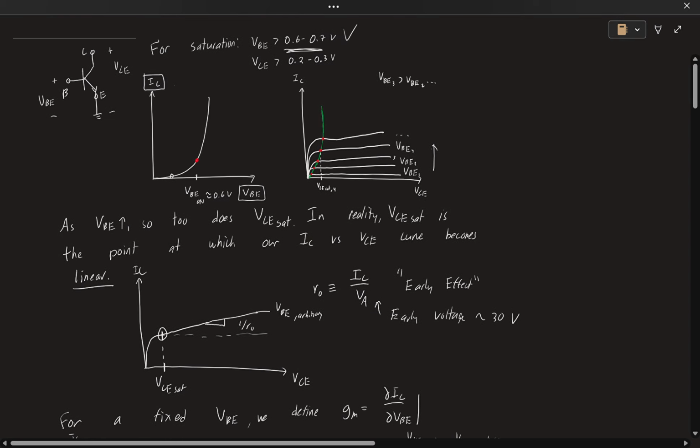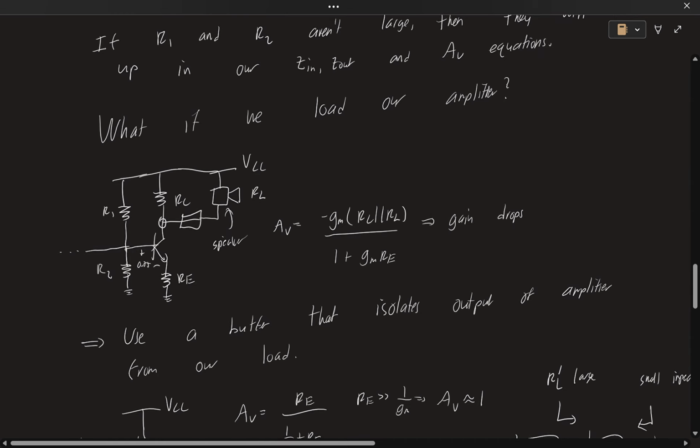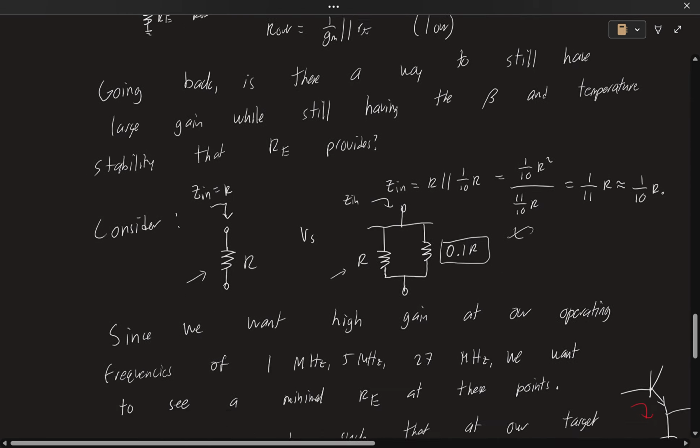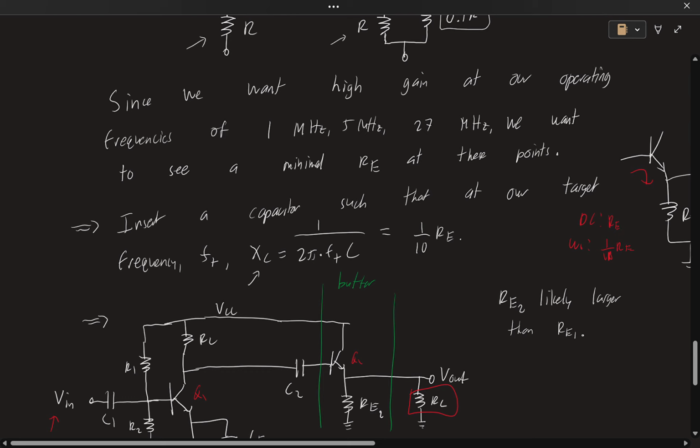I guess there may be one more thing to mention. We typically use a lot of bypass capacitors and decoupling capacitors. And the main things that you should know, if you are confused by any of these impedance things, is capacitors are going to be open at DC, right? So they block DC. At high frequency, they'll be a short. And you should probably know their impedance equation, hopefully.